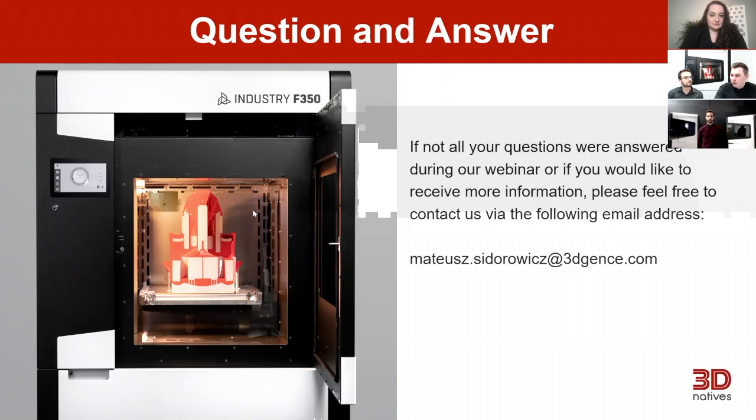We have, I believe, one of the examples. If you are designing something with small parts or fine detail, and you are using very high temperature printing material, this is a very, very short way to have troubles, because there won't be enough time for the temperature to get out of the place where the material is being built up in this one small place. So there are some requirements that you should follow if you can consider choosing the material before designing the part.